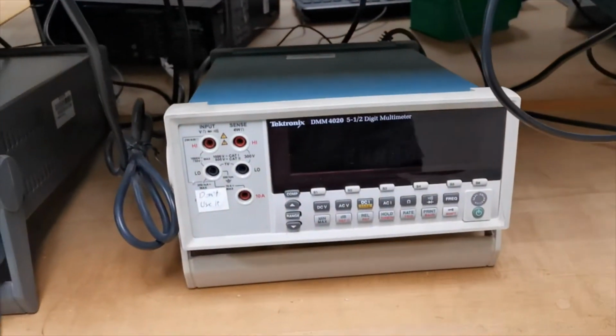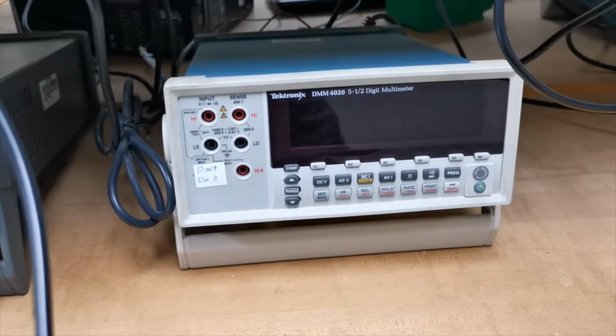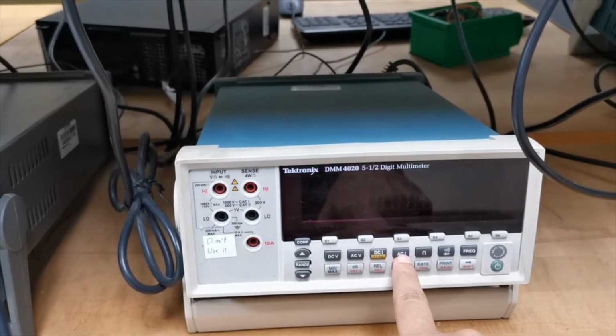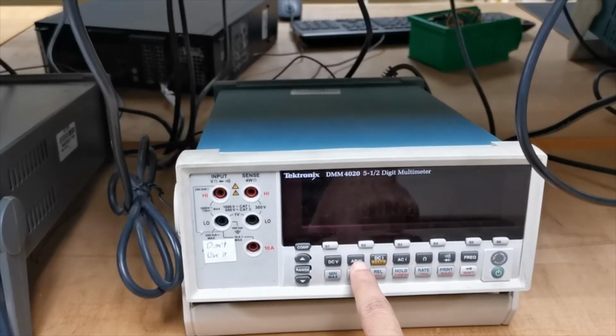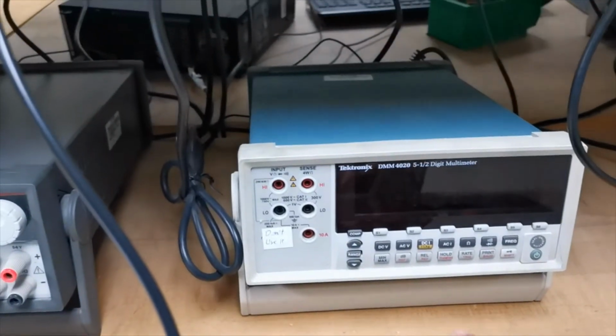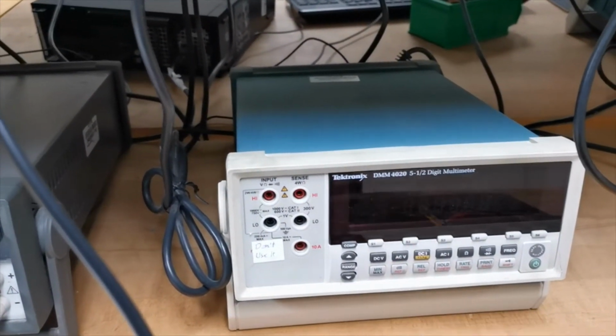Okay, the same thing we can also measure using the multimeter, since we have the AC here, you see AC volts, AC current. So I can also measure the RMS value. When I measure the voltage here, A and B, it will give you the RMS value of the voltage. Okay, let's do that.